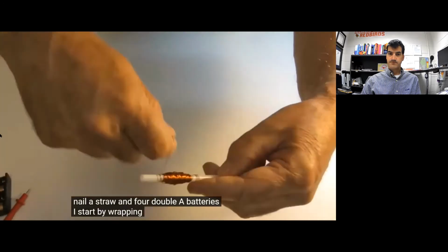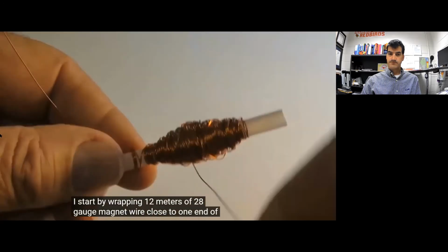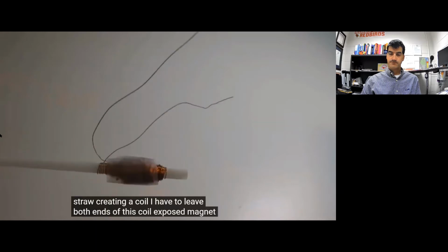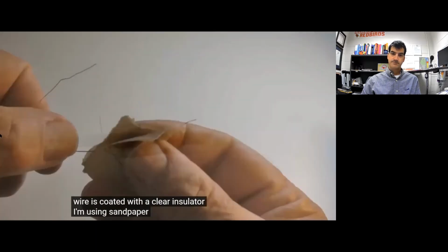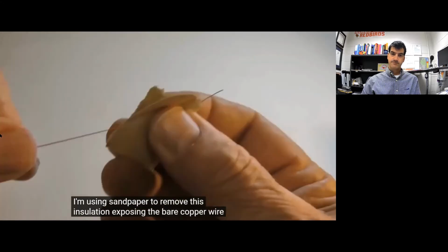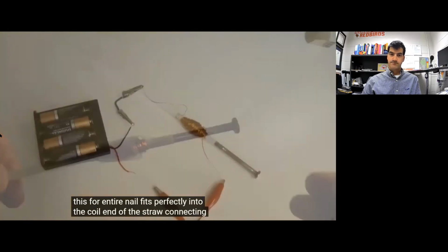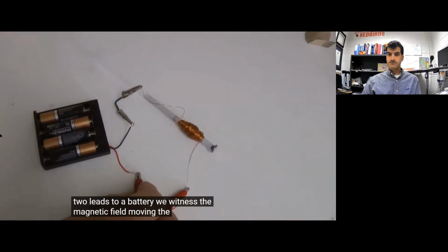I start by wrapping 12 meters of 28 gauge magnet wire close to one end of a straw, creating a coil. I have to leave both ends of this coil exposed. Magnet wire is coated with a clear insulator. I'm using sandpaper to remove this insulation, exposing the bare copper wire. This 4-inch iron nail fits perfectly into the coil end of the straw. Connecting the two leads to a battery, we witness the magnetic field moving the iron nail.